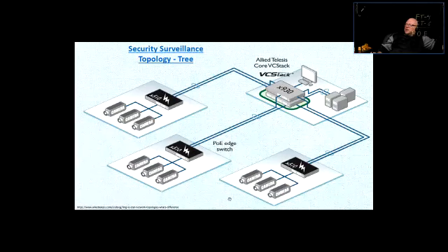So you will have maybe 3, 4, 9, 12 cameras, 24 cameras, and the cabling will be locally distributed into that switch. And over here, you would just have one, maybe fiber optic link or a couple of Ethernet cables, instead of having all from here to each individual location. Plus, you can only have 300 feet when it comes to Ethernet, so sometimes remotely located switches are the only way to solve that if the distance is greater than 300 feet end to end.